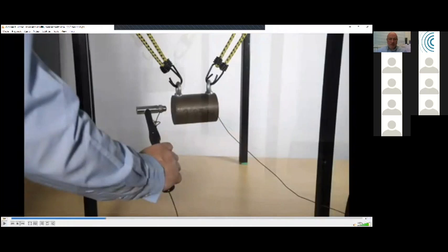We have force, we have mass, we have acceleration, and force equals mass times acceleration. Now, because of the way we've set up the analyzer, the reference quantity is force, and so we have acceleration over force, which is a quantity known as accelerance. And we can work out, if we rearrange the equation, that that's actually equal to 1 over the mass.